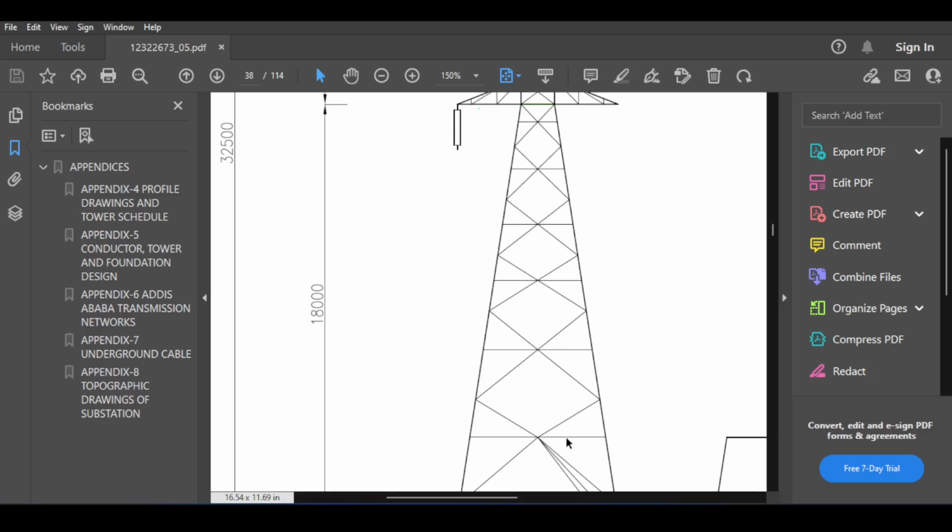and what is my suggestion to this, the answer is really, I don't know, to be honest, because it depends, and this is a really nice idea to think about. If you increase the number of elements here, well, you decrease the load per member, decreasing its weight, but you are increasing the number of members, increasing the total weight of the structure. So there is like a minimum point where you get the best possible weight, the best possible combination of having an adequate number of members and having the smallest weight.